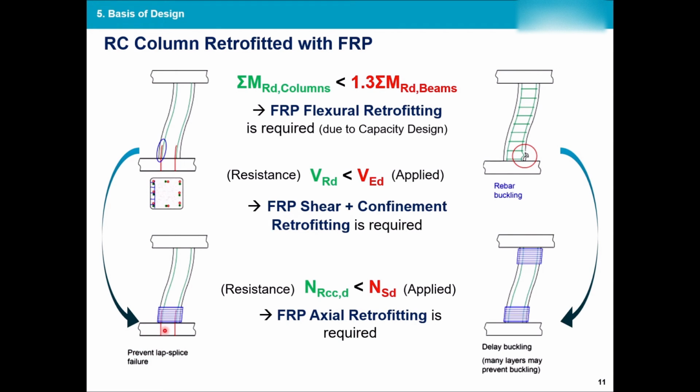As you know, whenever two reinforcements from different components, in this case the footing, come inside the column, this is the way that we connect these two components to act as a system together. There will be some spacing, which we call the lap splice. The code has some dimensions for it, but failure usually happens over there massively because these are two different reinforcements just coming and tied together with very thin steel material.